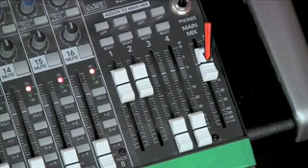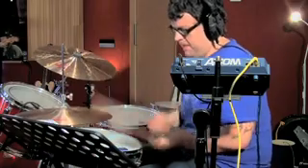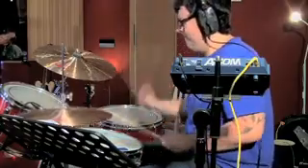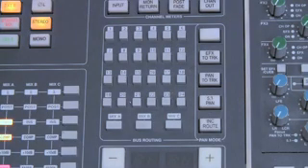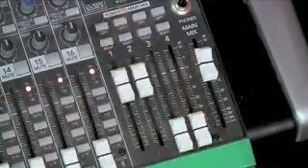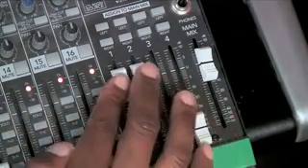The master fader is the fader that controls the main output level of the console's mix bus. The subgroup outputs and their controls can also be found in the master section. Subgroups are used to merge various channels as an additional level control before the master fader. Typical use would be to group similar instruments to one fader once a balance has been achieved on the individual channel faders. A console would usually have some type of routing matrix or subgroup routing switches on each channel. On some consoles, the subgroups have dedicated outputs and can be used as a way to control and choose which channels are sent to your recording device.